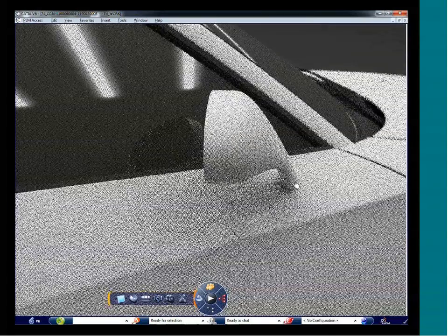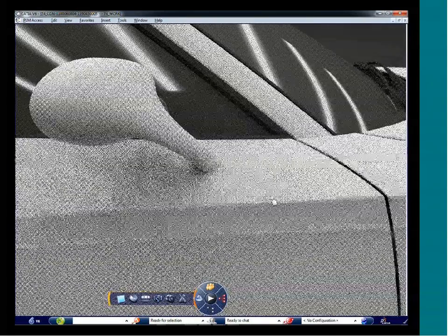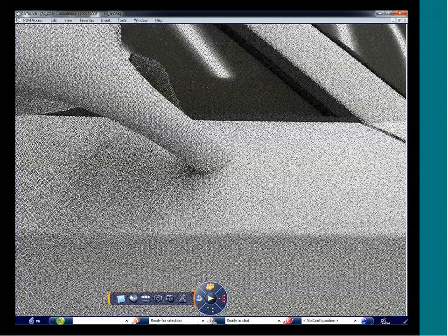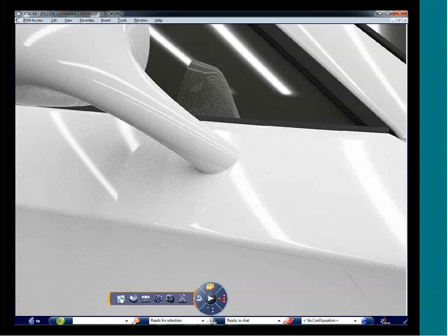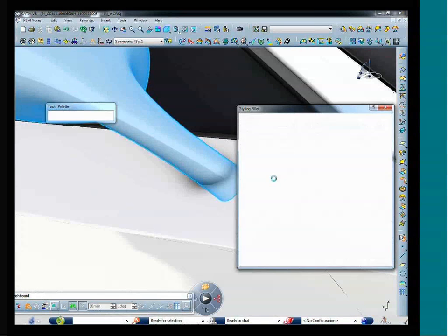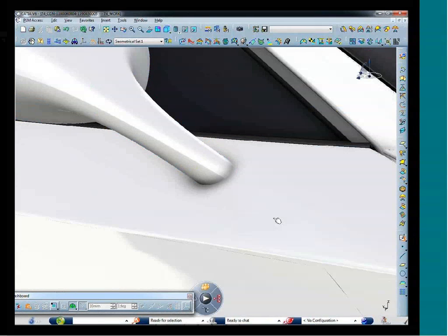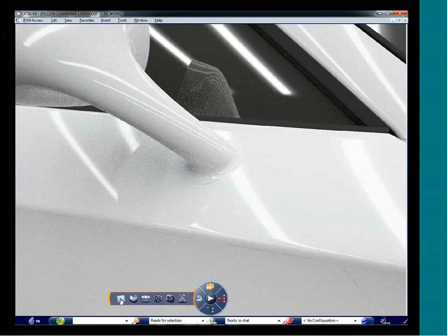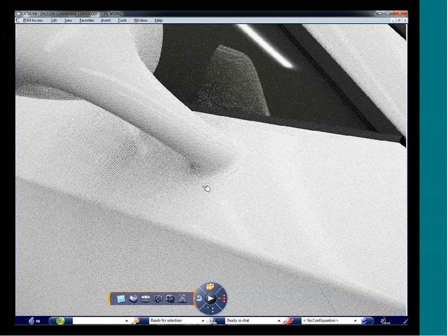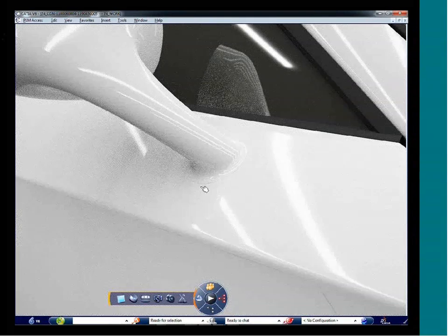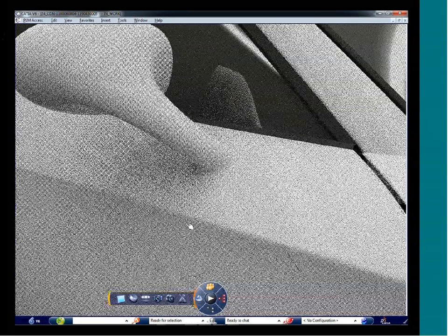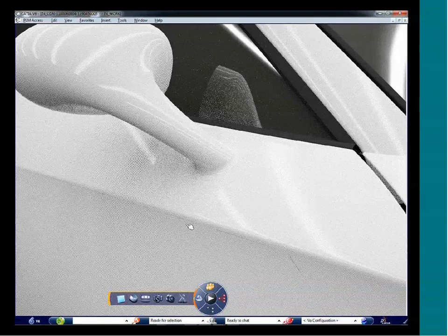You can see reflection in the body of the car and also on the windows. And here we can notice that there is no fillet between the body of the car and the side mirrors that I just created. And so to create this fillet, I can just use CATIA HM to do that and to combine those two, subdivision and CATIA HM surfaces. And as you can notice, we can also check the quality, the kind of zebra, directly with a physically correct visualization of CATIA Live rendering.